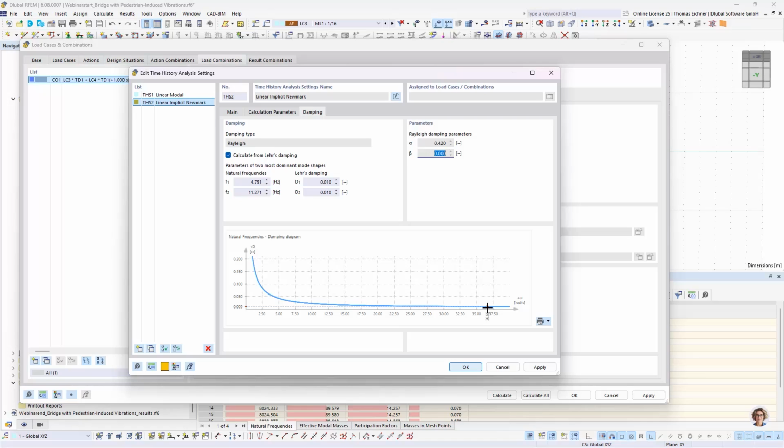So if there's a really, really stiff object in the model that could be on some value of 30 in this diagram, then that would result in extreme convergence problems. With setting this to 0, you wouldn't have the problem of an infinite damping for whatever frequency. I mean, except if you're in the first range, but that's another topic.